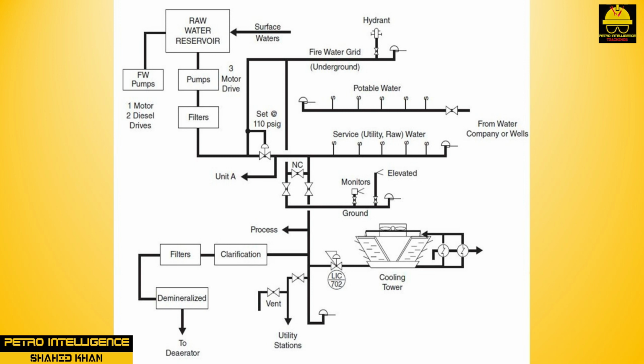Note that operations at some plants can differ greatly from those described in this course. The fire water pumps are instrumented to start automatically when the fire water system pressure declines below 110 psig. The first backup pump starts at 110 psig, the second diesel-driven pump starts at 100 psig, the third diesel-driven pump starts when the system pressure drops to 90 psig.